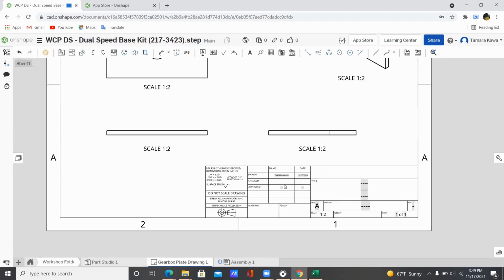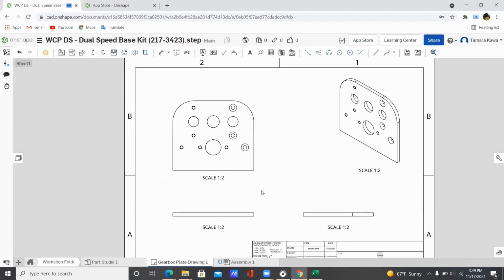basically it's the size that you have scaled this to put onto the sheet. So if your part is 1 to 1, then the dimensions of it on the sheet, yeah. So generally you do want to scale something down that way it actually fits on the sheet. Like if you have a 60-inch bar, obviously you need to scale that down.